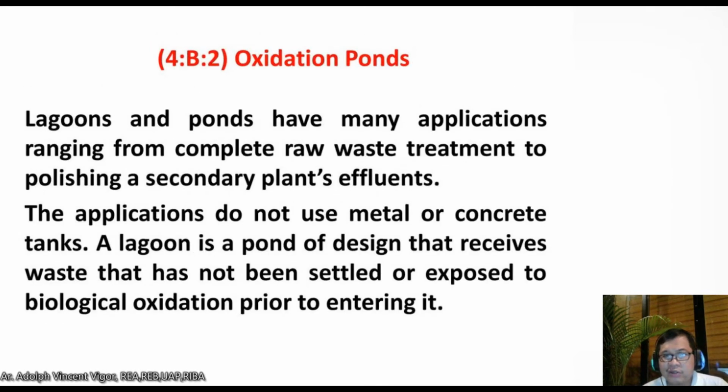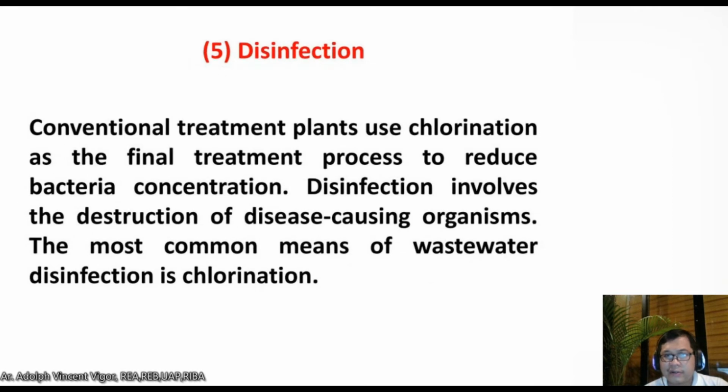And for oxidation ponds, lagoons and ponds have many applications ranging from complete waste treatment to polishing secondary plant effluents. So the applications do not use metal or concrete tanks. A lagoon is a pond designed to receive waste that has not been settled or exposed to biological oxidation prior to entering it. So fifth, we have disinfection.